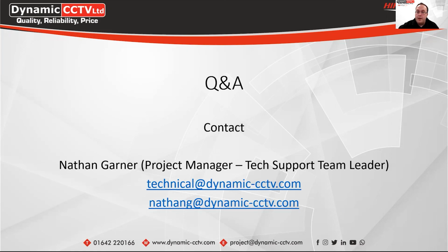Lee's asked, are all K-series upgradable with EY4? So yeah, the K-series NVR, as long as it's an NI-K, those can be upgraded to the EY4 firmware, which is available on the Hikvision UK portal. There's a link to those on our website to take you directly to them.